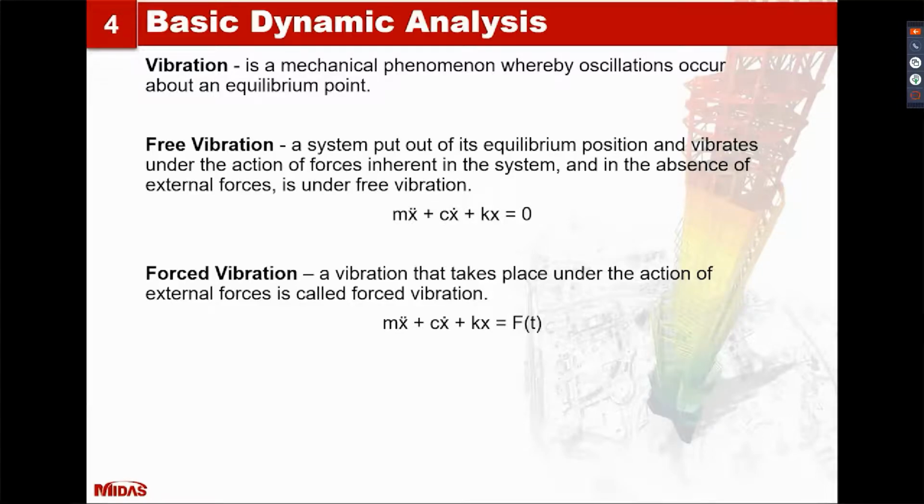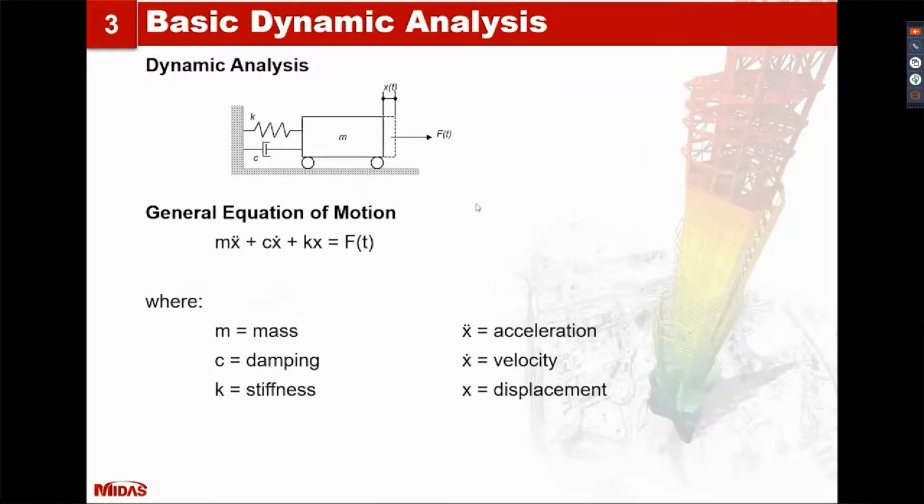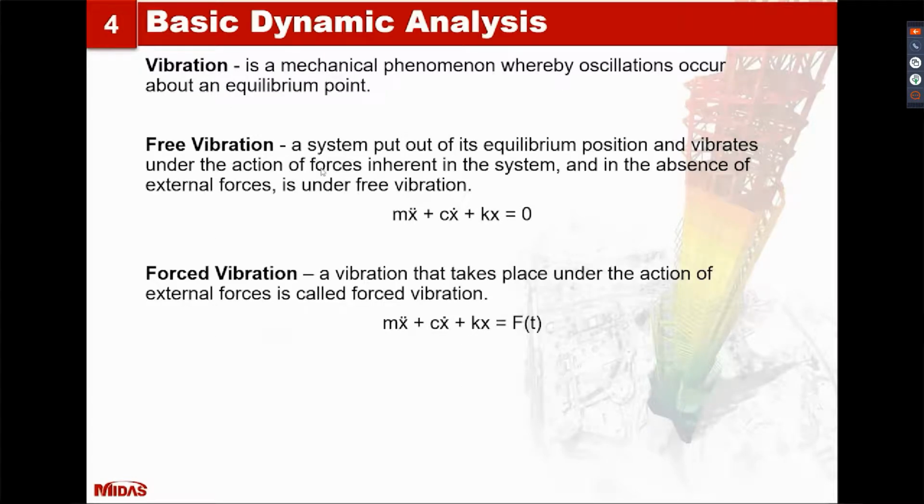Free vibration is when a system is put out of its equilibrium position and vibrates under the action of forces inherent in the system, and in the absence of external forces is under free vibration. So meaning to say, if you have this vibrating block, you set it on an initial displacement and then you let it go, and then it continues to vibrate until it stops. So that is the free vibration.